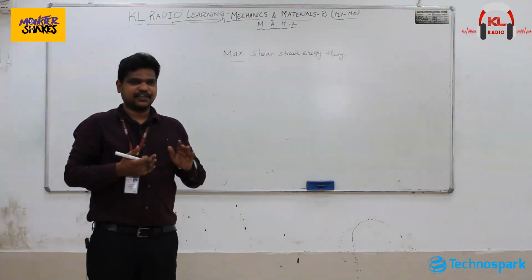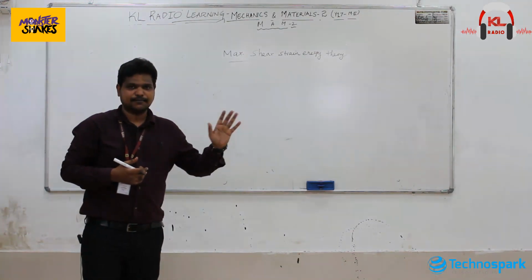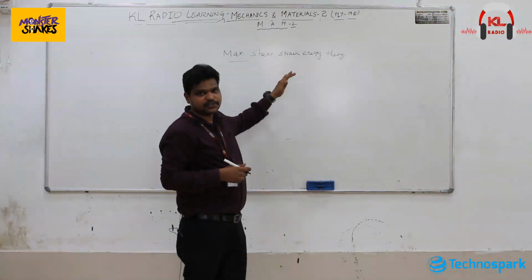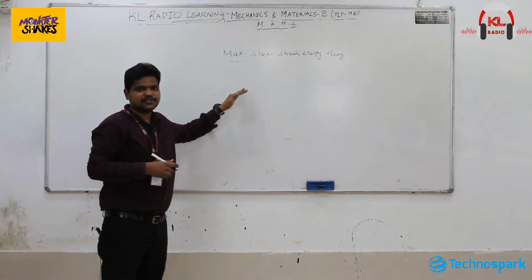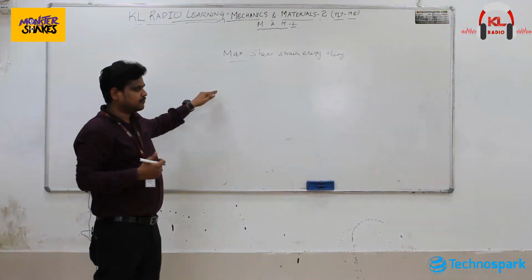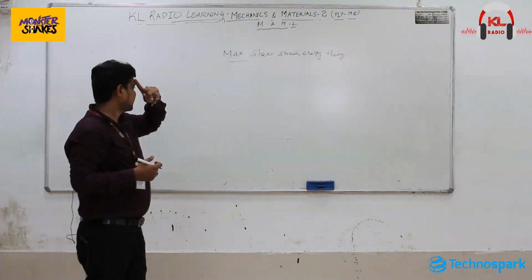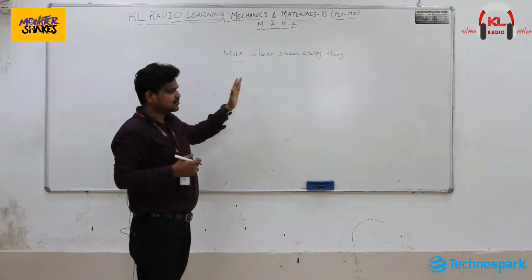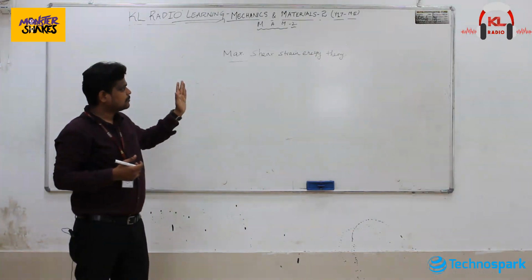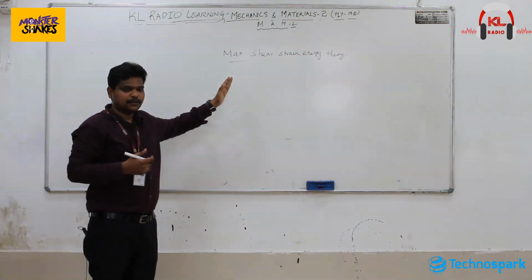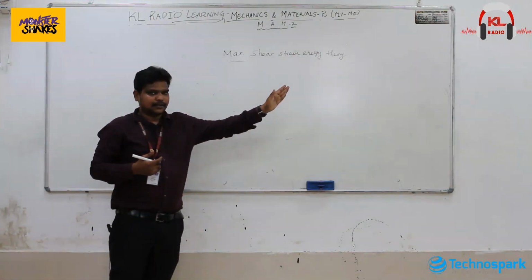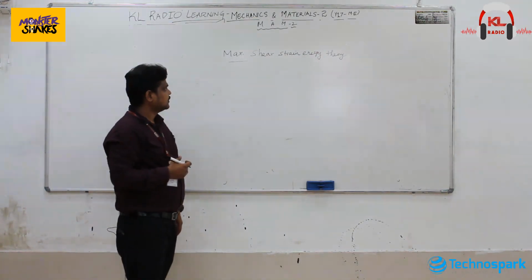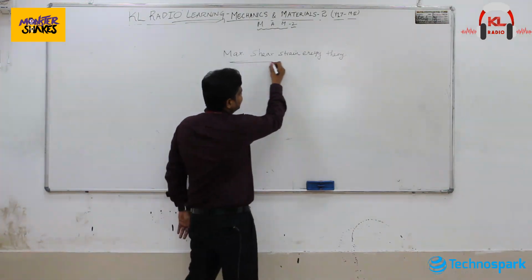What is the difference between maximum strain energy theory and maximum shear strain energy theory? Before going into that, this theory is so important because it gives more accurate results for a material subjected to pure shear, even for ductile materials. This theory is also called the von Mises stress theory, and each theory has another name, but I am specifically mentioning this because students may often see this theory in design tools like ANSYS or Abaqus. So maximum shear strain energy theory, why is it so important?